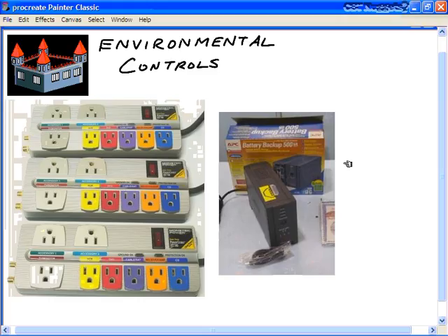Other things to keep in mind are making sure that you've strategically located your computer room to mitigate against the risk of flooding, for example. Maybe not put it in a basement where flooding is a possibility. If it's a multi-story building, probably the best location is somewhere that reduces the risk of fire, smoke, and water damage, like the third, fourth, fifth, or sixth floor. You want to do regular fire inspections. You want to fireproof the walls, the floors, and ceilings.